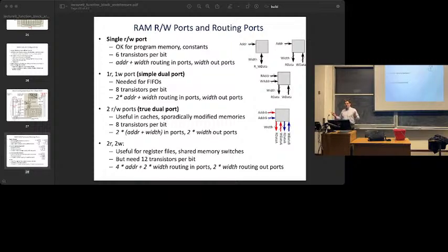What would I use this for? If nobody ever uses it, then I don't have to worry about it. What do you think? A FIFO? It's not a great match for a FIFO because, technically you could build a FIFO out of it, but basically you can only read in a cycle or write in a cycle. On a lot of FPGA FIFOs, you really want to be able to do both, rather than say you've got to wait. If you think of how we were using FIFOs to decouple modules and streaming computations, it's going to be really inconvenient if you say I can write into this or I can read from it, but I can't do both, because we're actually using them to figure out when to stall and so on. So yeah, not usually FIFOs.